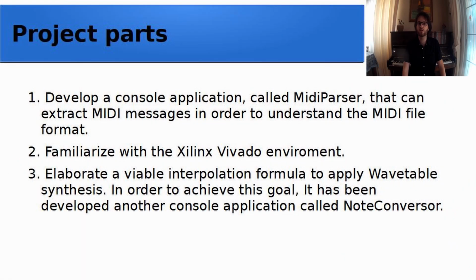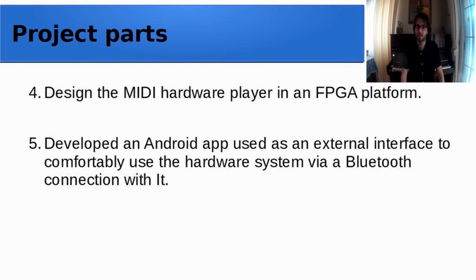First of all, in order to understand the MIDI file format, it was needed to develop a console application, called MIDI parser, that can extract MIDI messages. Secondly, it was needed to familiarize with the Xilinx XOHW20 environment. After this, it was needed to elaborate a viable interpolation formula to apply wavetable sound synthesis. In order to achieve this goal, another console application has been developed, called Node Converter. The next step is the design of the MIDI hardware player. Finally, it has been developed an Android app, used as an external interface to comfortably use the hardware system via Bluetooth connection.